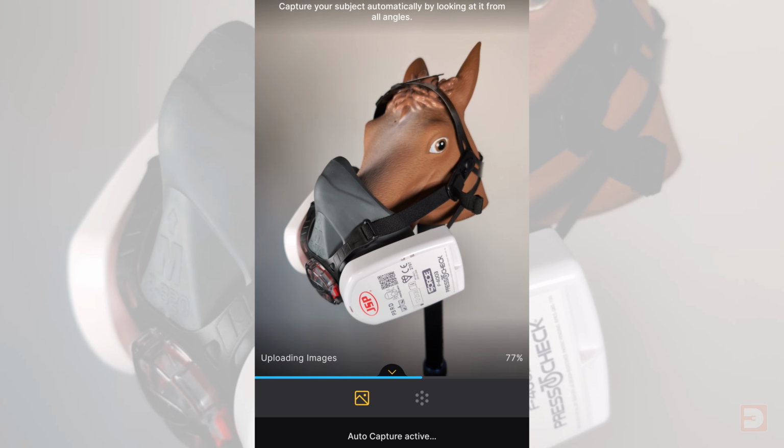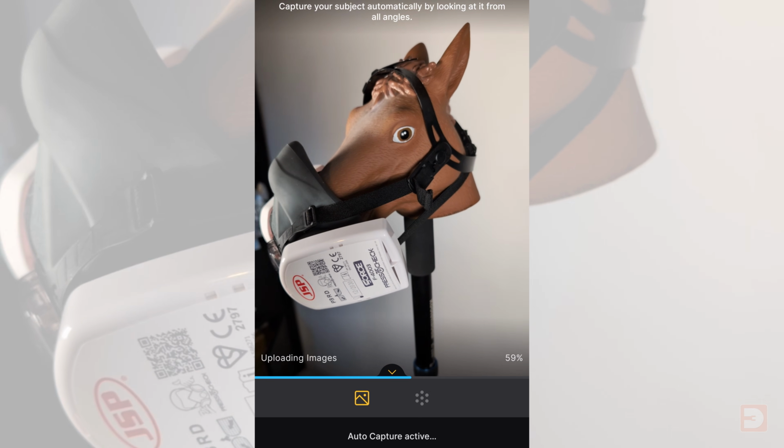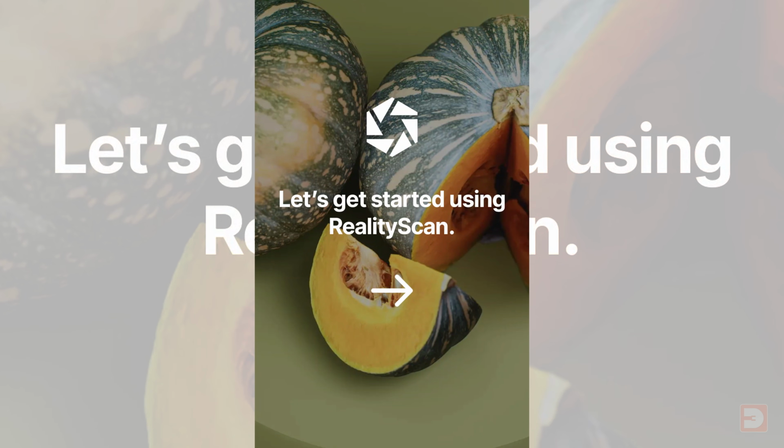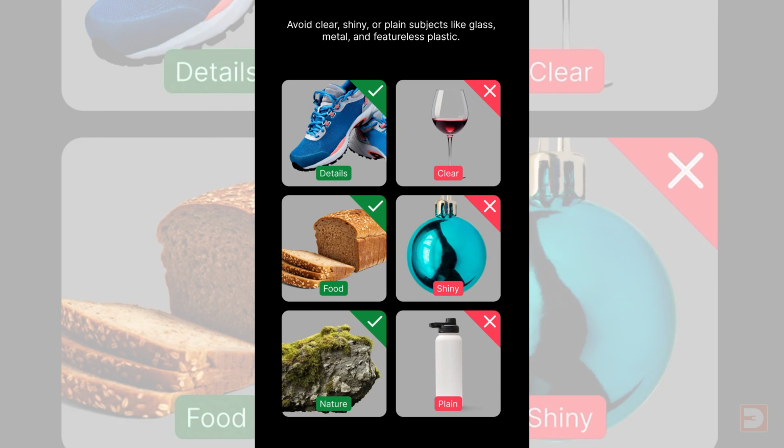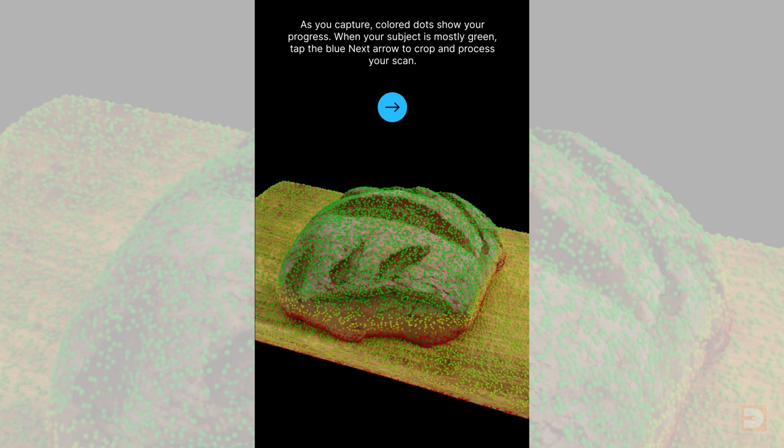You'll also need software to process the images, and there's a couple of ways you can go with this. There are some mobile apps available, so you could just take the photos on your phone and then just upload them directly for processing server-side. For the most part, these mobile apps tend to either produce models of limited detail, or you need to pay for server-side processing. Either way, doing the whole thing on your phone can limit the control you have over the results. The other option is to do the processing on your computer. There's a wide range of software available, and if you want to produce high-quality photogrammetry scans without paying for server-side processing, this is the way to do it.